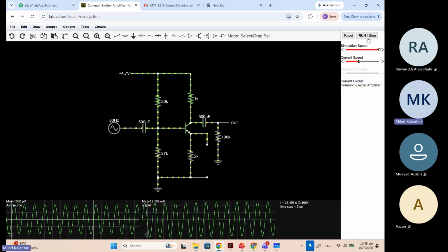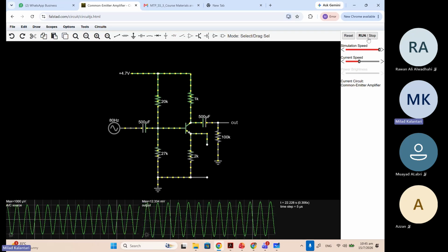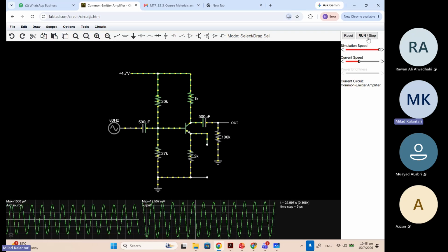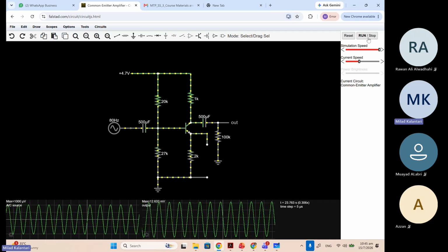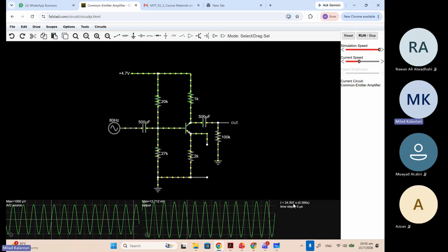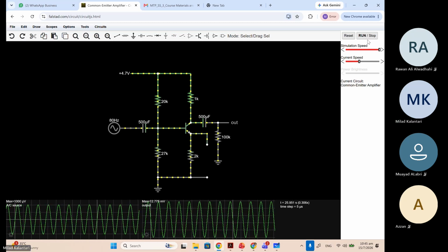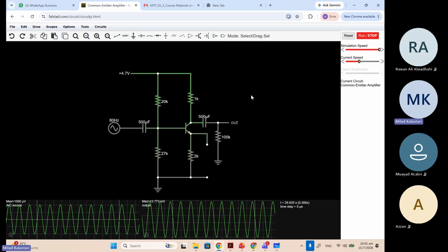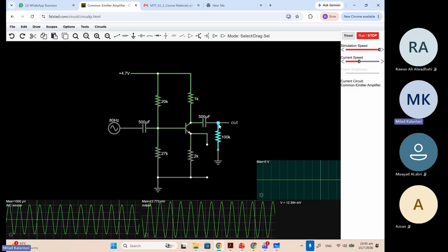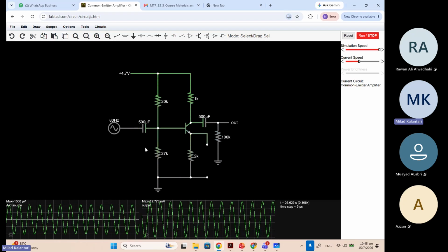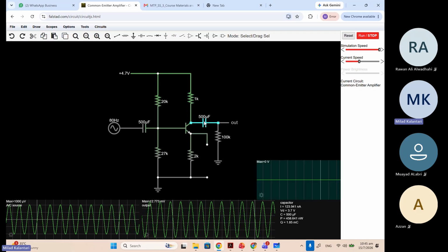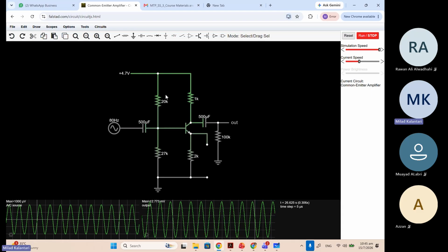Practically, we have to turn it on and wait a little bit. Yes, of course, but this simulation speed is less than the practical speed of passing time, almost, right? And this is also important. Once you design this, you need to design the values of the capacitors so that once it is turning on, the settling time is reasonable for your application. If too long, then sometimes you cannot afford it.